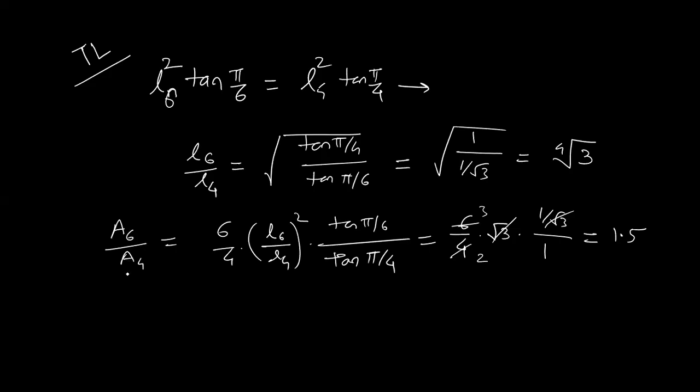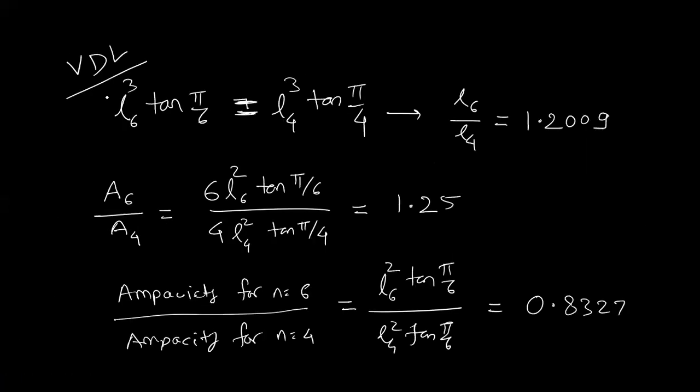But now we need to make the feeders thermally limited. That means we need to design the thermal insulation, the cross-sectional area, or the thermal properties or material of the feeder in such a way that it becomes thermally limited. So that guides the design process when we want the higher area. But suppose we want to save cost by not putting in more material, we can let the feeder be voltage drop limited with less area. Suppose we want a less costly solution, that is a design choice.